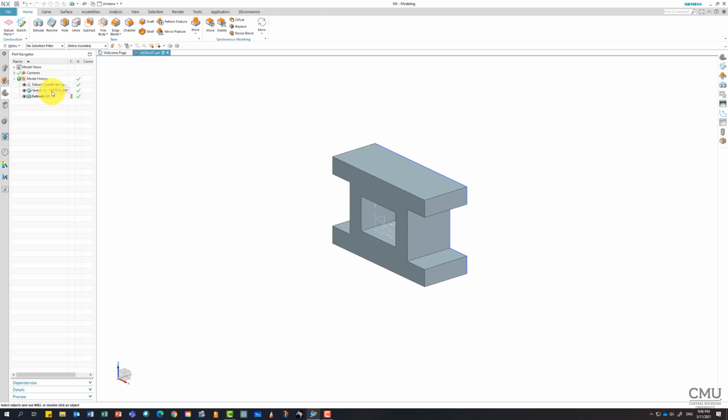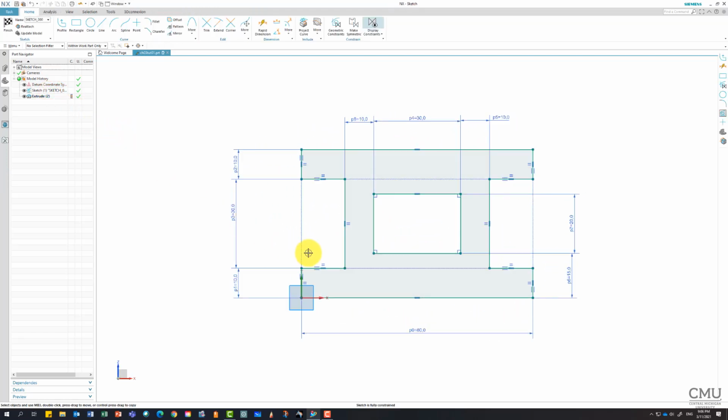So the key point is when you do a sketch, try to get to the shape or profile as quickly as possible with the mouse point, but be careful with the size. If you're making it way too big or way too small, as you later add the dimensions, it can really distort the whole shape. So try to be careful, but by using the mouse click, it can be done fairly quickly. Then start adding the constraints.